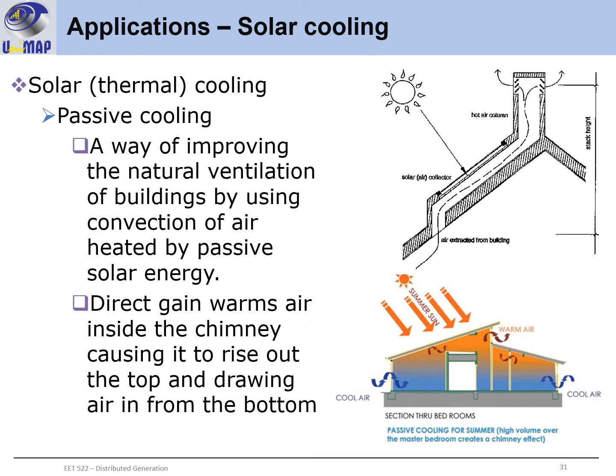Okay, this application of solar is unique. We use the solar energy from the sun, and by having a specific design of the house, it can have a natural ventilation system. So like this, if we have a hot summer sun, the air inside the chimney will be heated up and will be very hot.